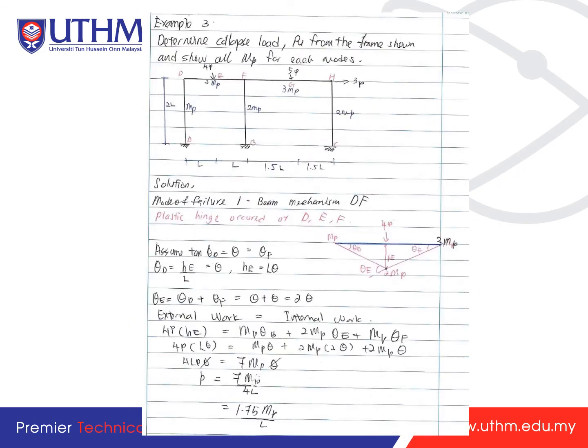So let's look at the solution of this. You can see how many reactions we have. The reactions here are 9 because it has 3 fixed supports. And the redundants we have is D is equal to R minus 3, so it's equal to 6. Then how many positions of hinge we have here.